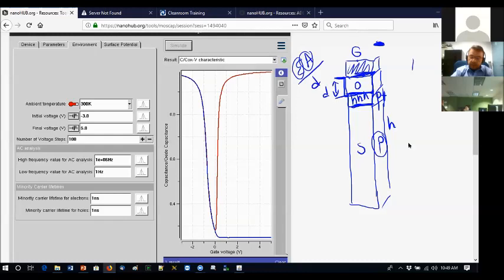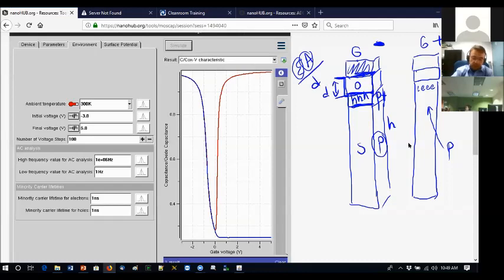Now, let's do something differently. We had the gate voltage, we had the oxide, we had the silicon here, again P. Now we applied plus, okay? In that case, what will the plus attract? Even though this is supposed to be a P site, it will start attracting the electrons here. But I have holes here too, so let me show the holes with a different color.